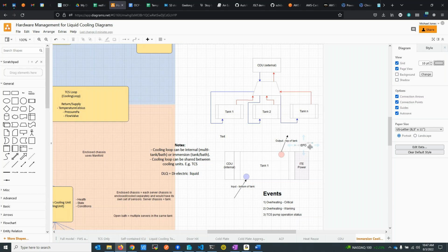Well, the standard server breakdown scenario, regardless of the cooling methodology, is you monitor the die temperatures of all the critical chips, and there's a fallback for dropping clock speeds and voltages to the chips if they start to get up to, say, 125 degrees C or so.